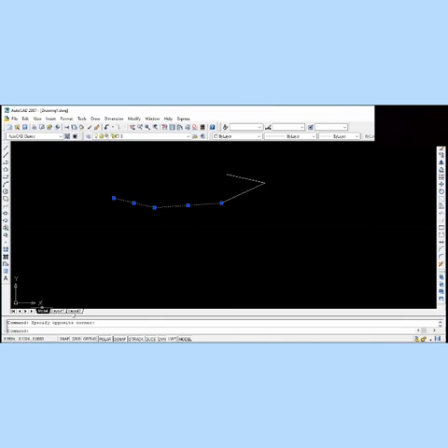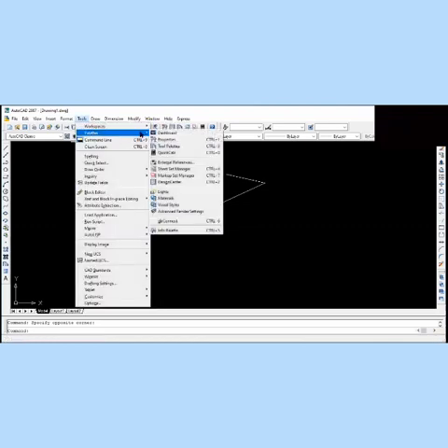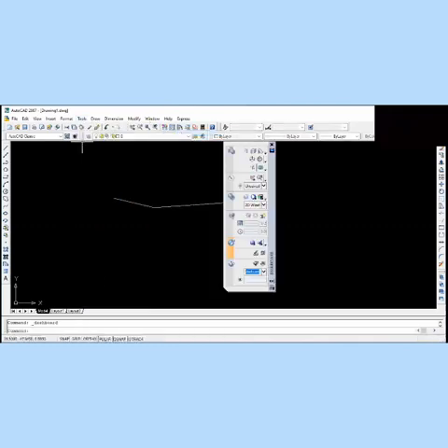So now, we also have what we call the dashboard. To display the dashboard, all you need to do is go to your tools menu. Remember, this is your menu bar. You go to your tools menu and then click on tools. Once you click on tools, you come to your palettes, and then click on dashboard. You can see this is what we call your dashboard. So now let me close it again.